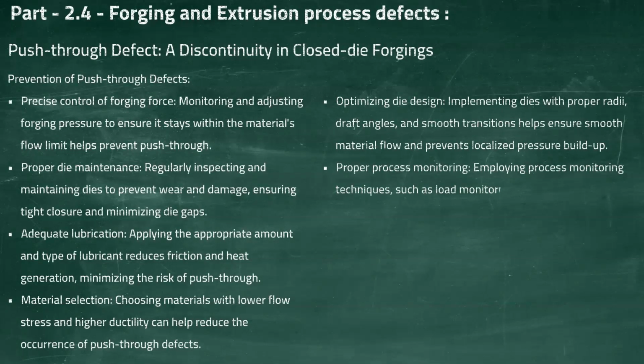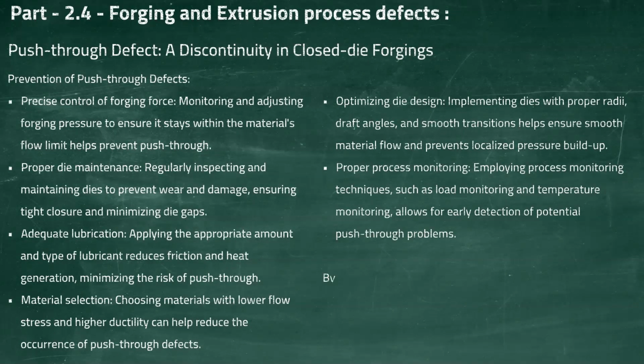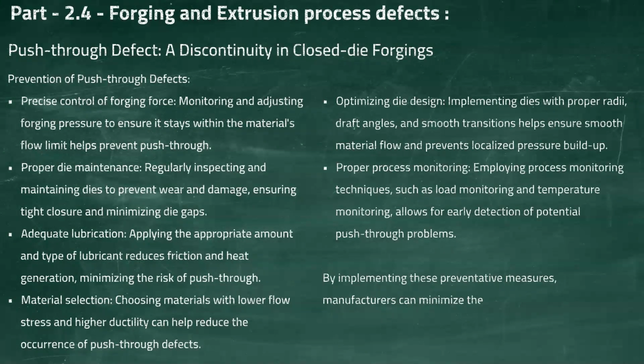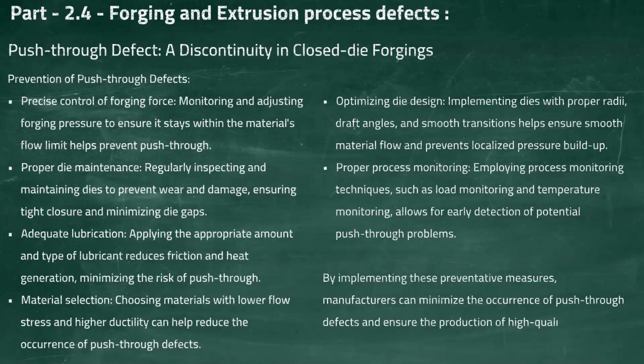Employing process monitoring techniques, such as load monitoring and temperature monitoring, allows for early detection of potential push-through problems. By implementing these preventative measures, manufacturers can minimize the occurrence of push-through defects and ensure the production of high-quality forged parts with consistent dimensions and surface finishes.